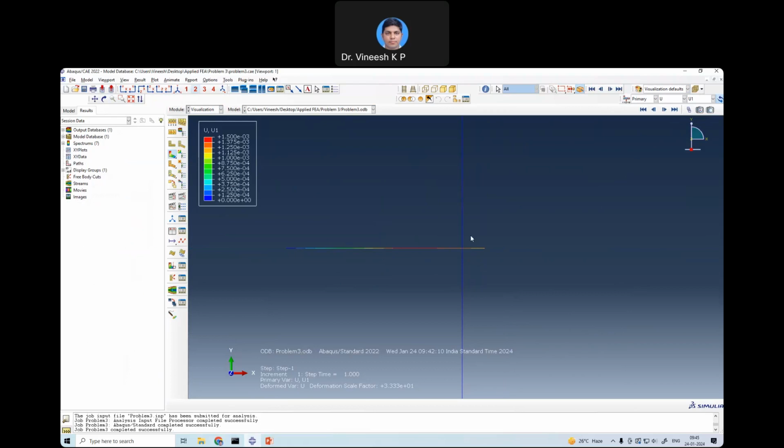If the displacement is 1.2 millimeter, on the screen you will not see 1.2 millimeter. Abaqus is going to magnify it. So maybe 20 times magnify it and show it. That is why you can see that even though the displacement is showing 1.2 millimeter, it is crossing the limit. So in reality, it will never cross. So for seeing that one, you are having some option here.